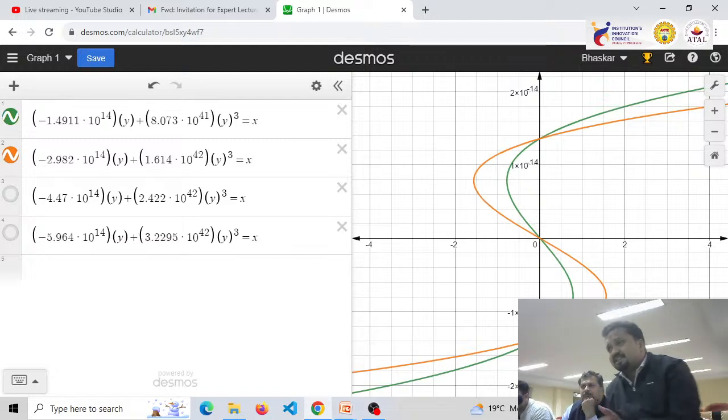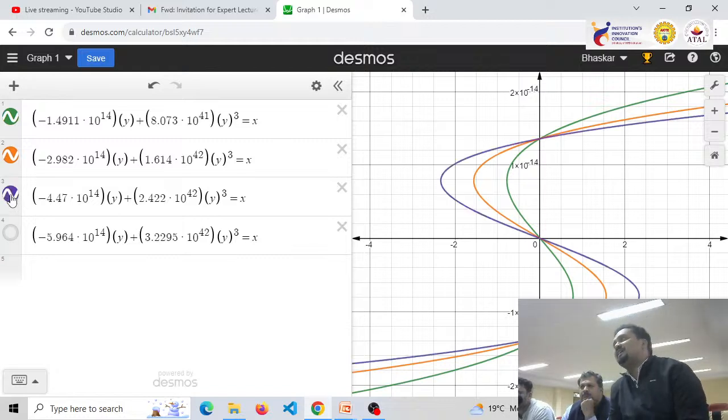So as I'm increasing the voltage, charge is decreasing, which confirms the presence of negative capacitance. Next, similarly, the thing which I did for 30 nanometers and for 60 nanometers, the same thing I am going to do for 90 nanometers.